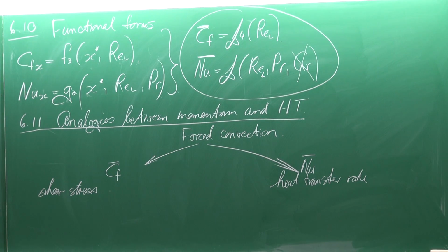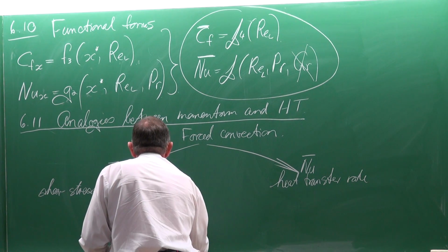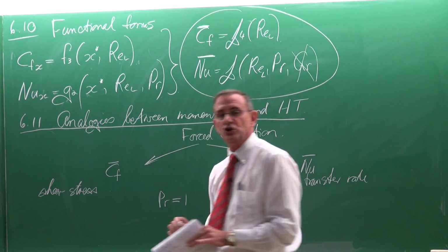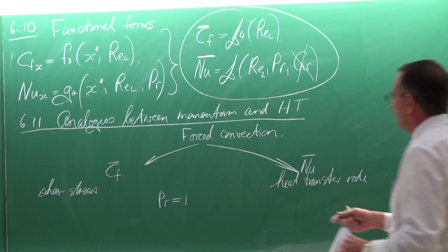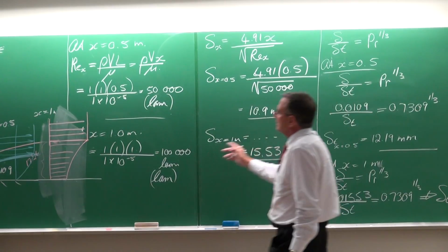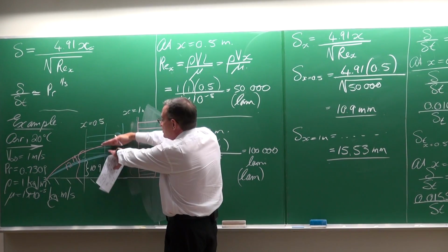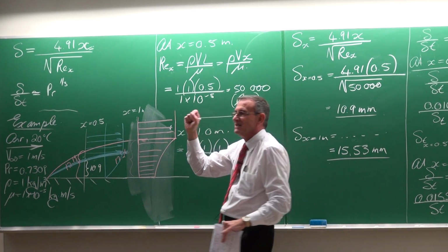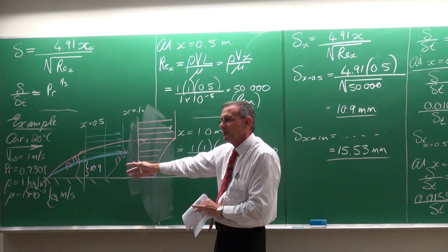And then it shows a very, very elegant solution for those equations that I've showed to you by using the special case of a Prandtl number equal to 1. So if we just go back to our equations also, we can see that if Prandtl number is equal to 1, it means that these two boundary layer thicknesses are going to be exactly the same. An order of magnitude, that's typically what happens with air.